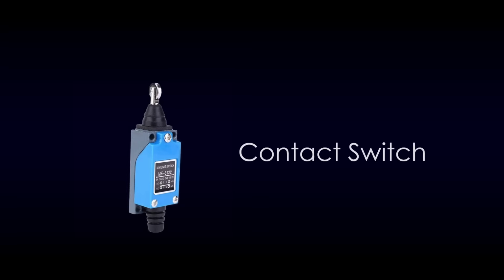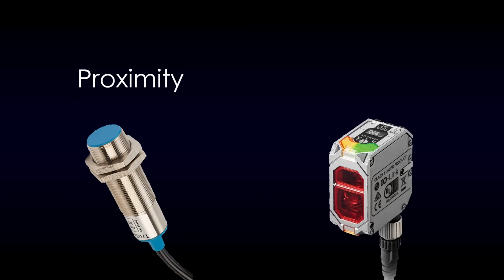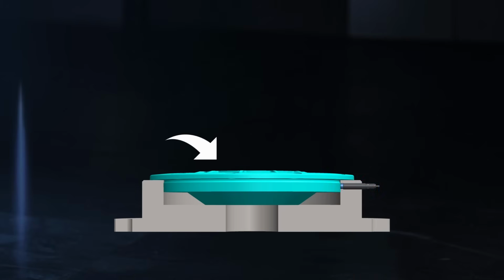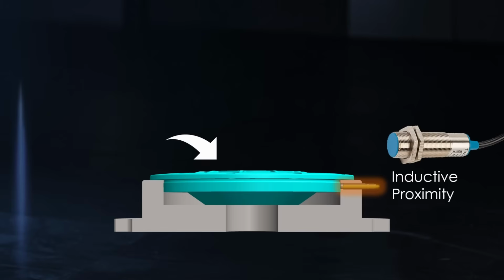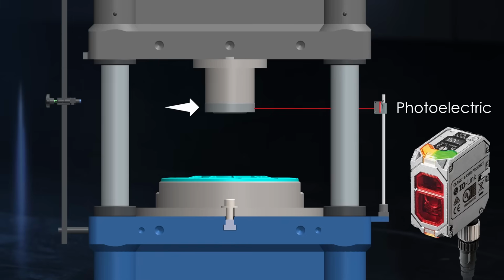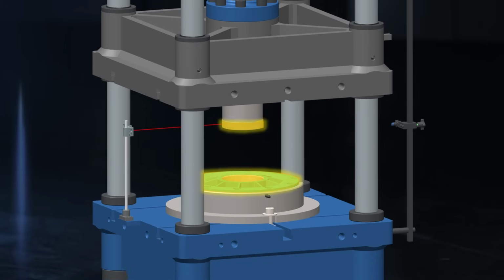These can be contact type switches, limit switches, or non-contact sensors like proximity or photoelectric sensors. In this setup, the housing is metallic, so we will use an inductive proximity sensor to detect it. And for the bearing, since we cannot place the sensor too close, a photoelectric sensor would be better. It can detect from a distance. So when the operator loads both components, these sensors detect their presence and send a signal to the PLC or controller confirming that the machine is ready to start.